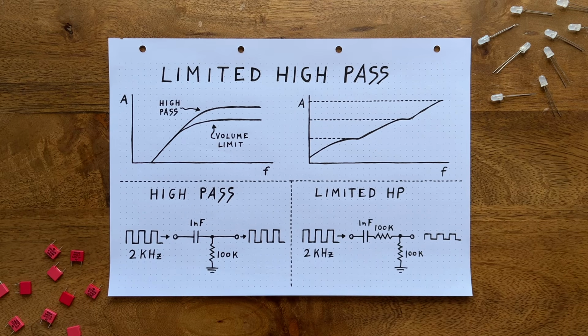Now, by placing a resistor after the capacitor, we give this path a default resistance, just like we've done for the shell filter. The effect is different though. Instead of letting a baseline amount of high frequencies pass through, we set an upper volume limit for them. That's because where before, high frequency oscillations could pass through the cap as if it wasn't even there, now they have to fight this resistance. Heads up though. As a side effect, doing this will move the cutoff point to the left, simply because we also increase the total resistance between our capacitor and ground, causing it to fill up more slowly.